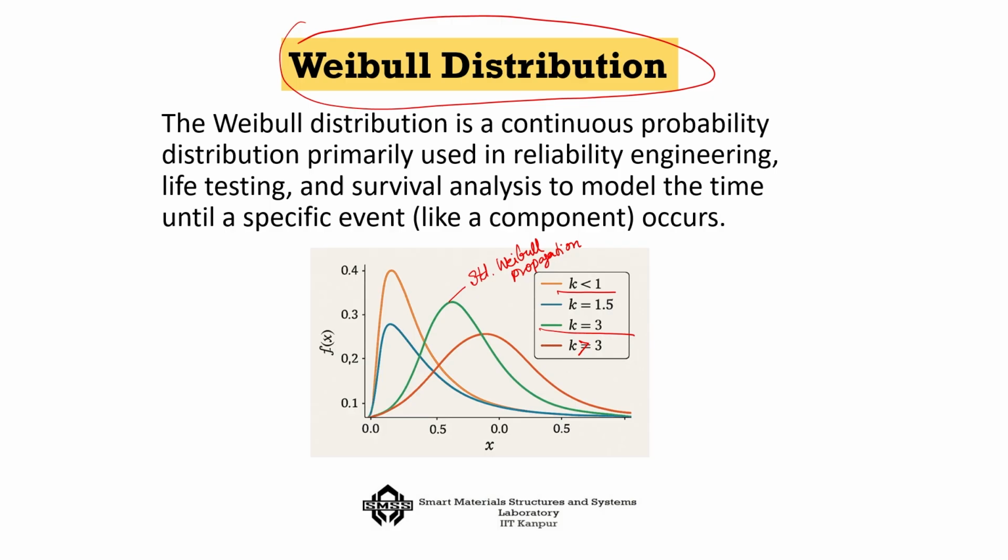Now, what is the significance of it? The significance is that in general most of the systems will have this type of a distribution, be it in terms of strength, let us say. So, for a material which is, let us say, like a ceramic material, you would see that a large number of samples will have their strength in this region. However, there are some samples which will have very low strength, or some samples which will have very high strength. Okay? Their numbers will be very low.